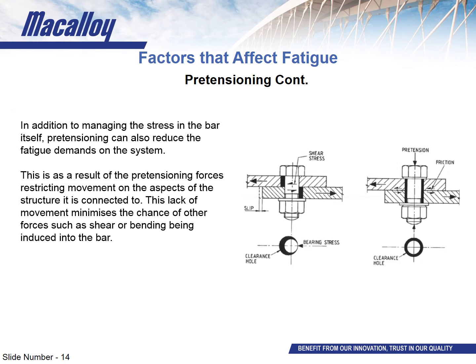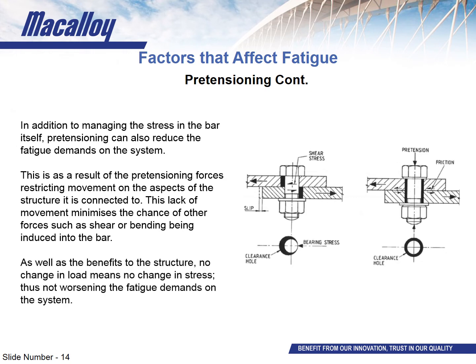This is due to the effect that the induced load has on the surrounding system. One such example can be seen in the diagram on screen now. The left-hand image shows a bolt that has not been preloaded. The two plates move when they experience force, and this in turn imparts a shear load on the bolt. If oscillating, this shear load can translate into a fatigue load and over time result in failure of the bolt.